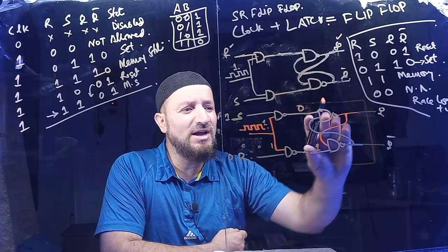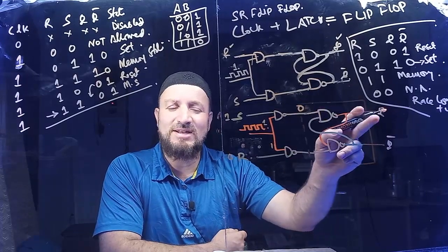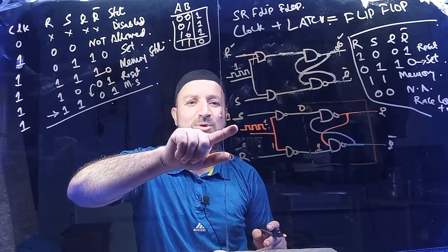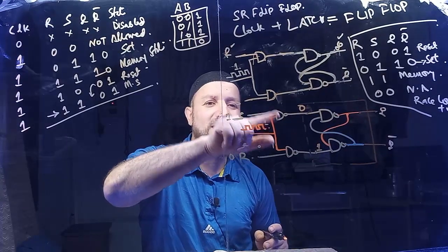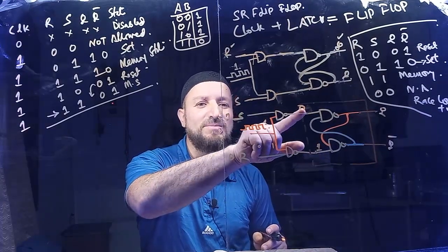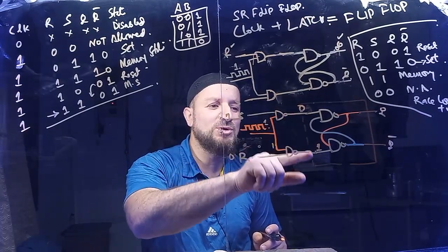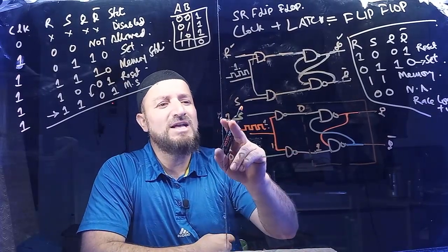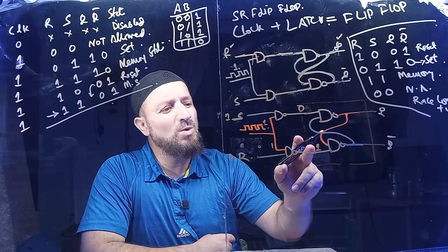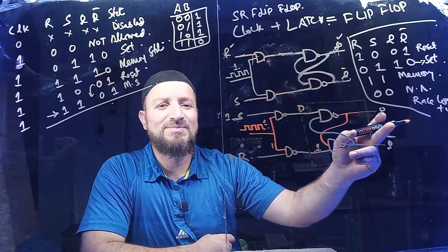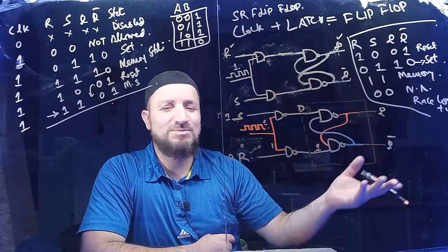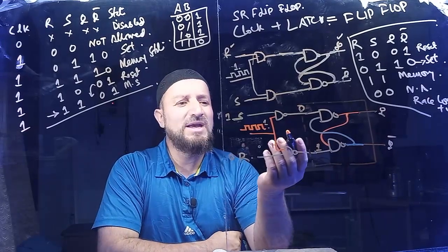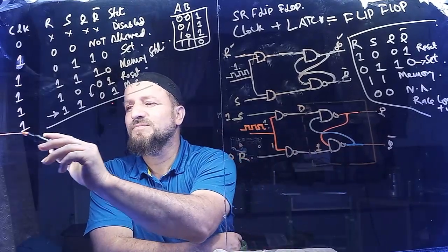And we know this circuit, if the 1 is on the bottom, it's going to set. Here I'm putting S as 1, but after the NAND, it is coming 1 here, 0 here. It was 1, 0, it becomes 0, 1. It flips it. That's what we want. We want S as 1, but for this circuit, when 1 comes here, it will set. Does that make sense? It's perfect, right? So let's try to make its excitation table here.